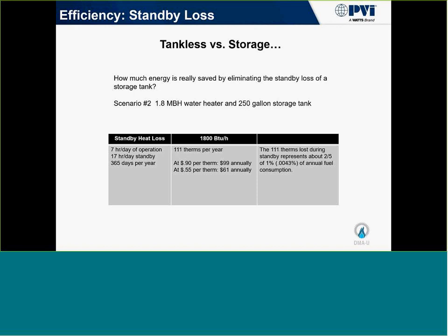Hey, Brett? Yes, sir. This is Jim Hoover. I would like to add to that, one of the misconceptions out there is that when you install a storage water heater, the standby loss has not been calculated into the efficiency test, and it is. It's the second part of the efficiency test. So when we're giving you the efficiency rating third-party certification on a storage water heater, that already includes the standby loss. There's no additional losses that are going to be incurred just by putting a storage water heater in. So if you're 95% efficient, that includes the standby loss calculation. That's a very good point, Jim. Thank you.